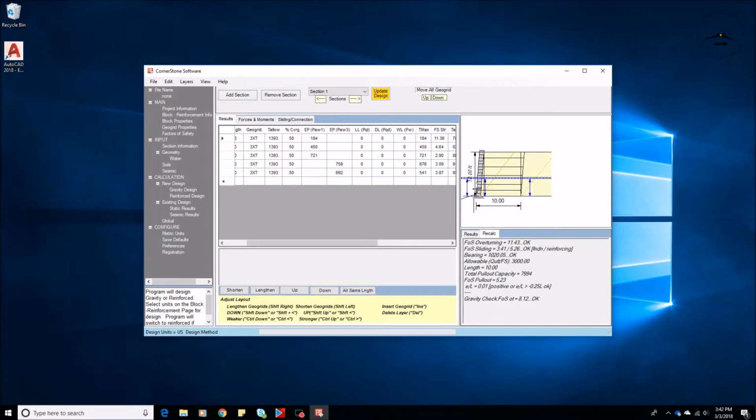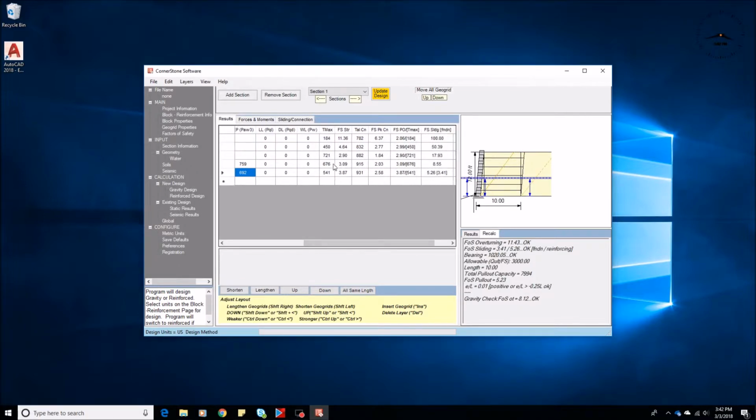And then our PaW3 is we're using submerged weights as a driving force. So we're calculating the earth pressure: P1 is the triangle above, P2 plus P3 is the water below. So we've got 759 pounds per square foot of water, 762. Our T max over here is adjusted for the water pressure.